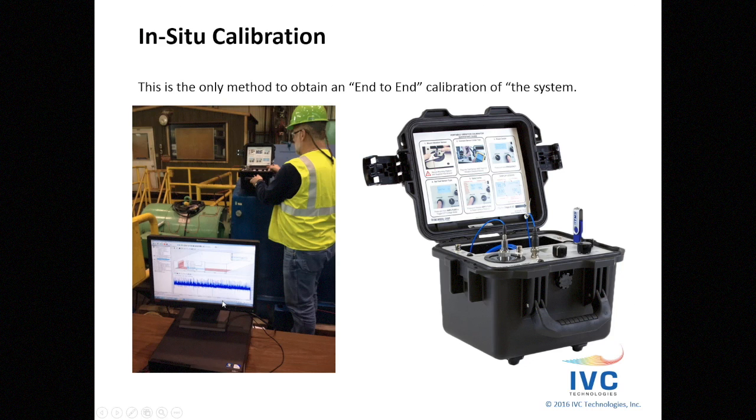So in that scenario, I'm actually calibrating the entire system from sensor, cabling, junction boxes, data acquisition, and even acquisition software and display software to verify and validate that I am getting good data and that the levels are what they should be.